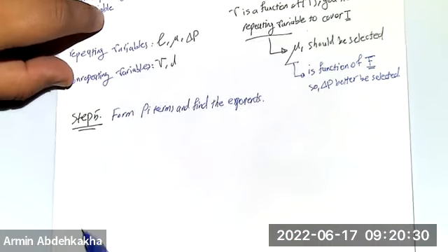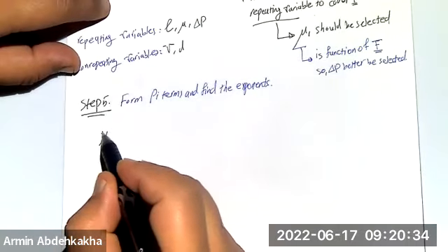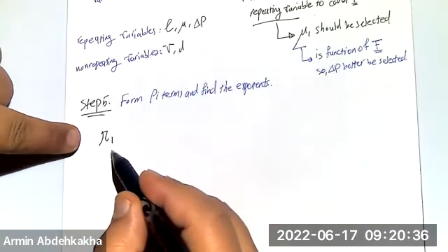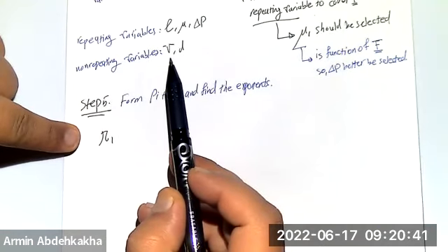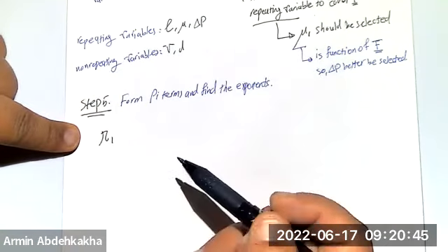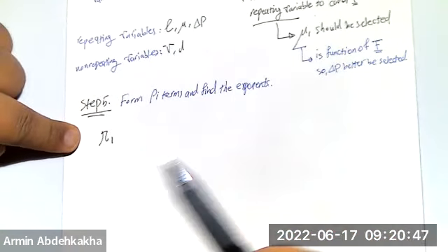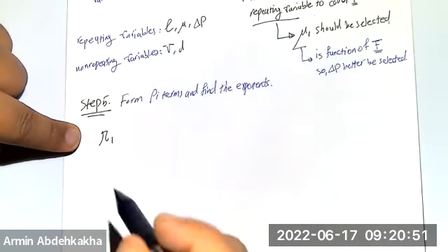Okay. So what is our Pi1? Pi1 always uses the non-repeating or dependent variables that the question gave you. So V comes to Pi1, and the rest that you decided to be repeating variables come to the other Pi term.